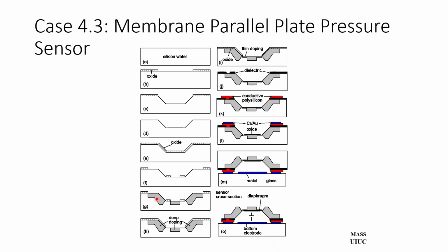Using the oxide, we use it as a doping window. So we heavily dope the regions that are exposed directly. And after that, we have the sculpted region as doped profile. The reason for this is because doped silicon has a much lower etch rate in silicon etchant. Then we grow a very thin layer of doping to form a shell, completing the sculpted shell.